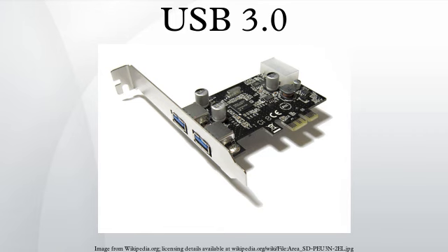As of 2011, this is often used to supply 2 to 4 USB 3.0 ports with the full 0.9 A of power that each USB 3.0 port is capable of, whereas the PCI Express slot itself cannot supply the 0.9 A.